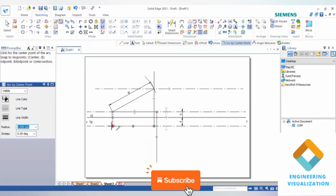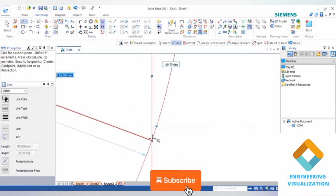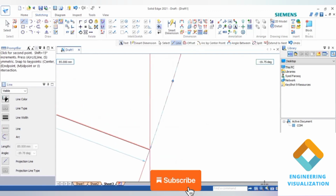Again go to arc by center and take the true length 85 mm. From the end points you cut the arc. And we join this cut point with the end point, you will get the another true length.